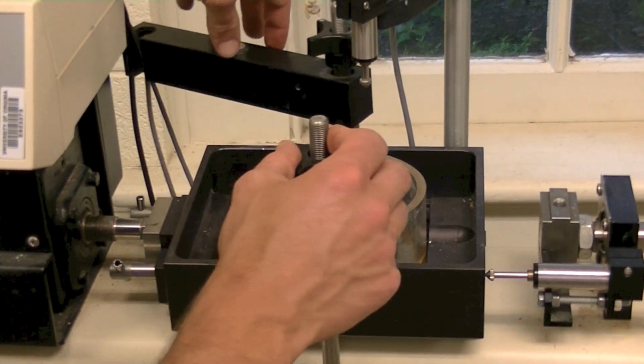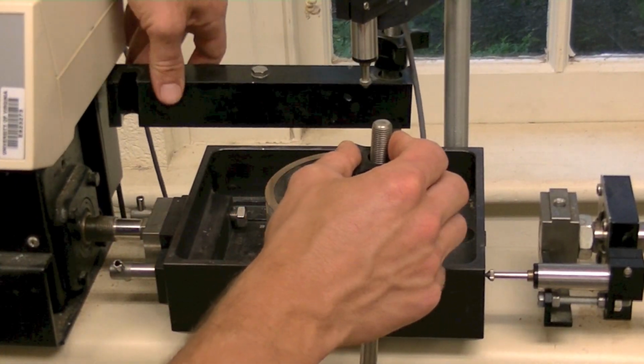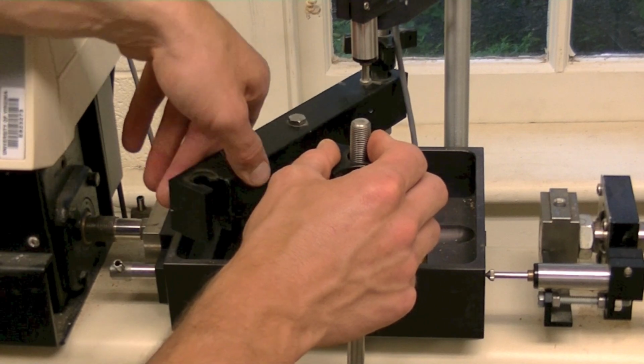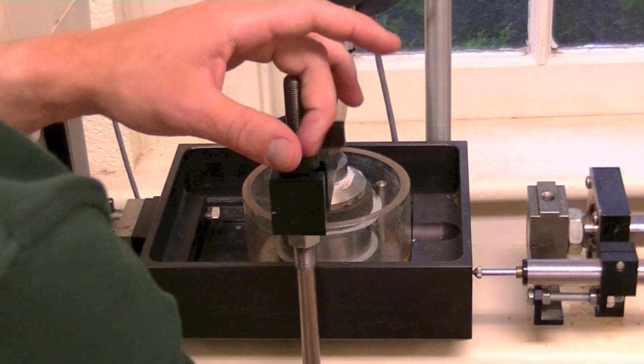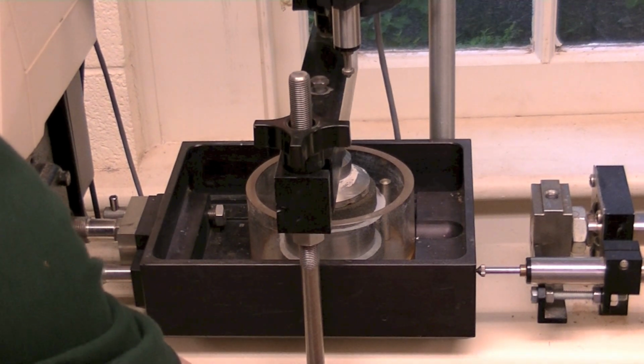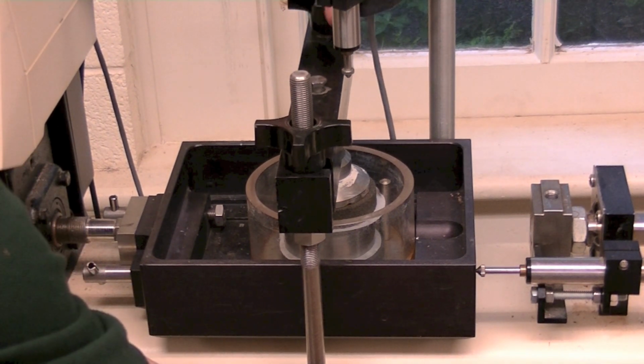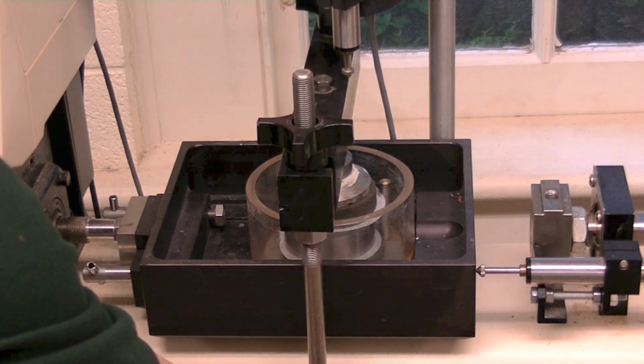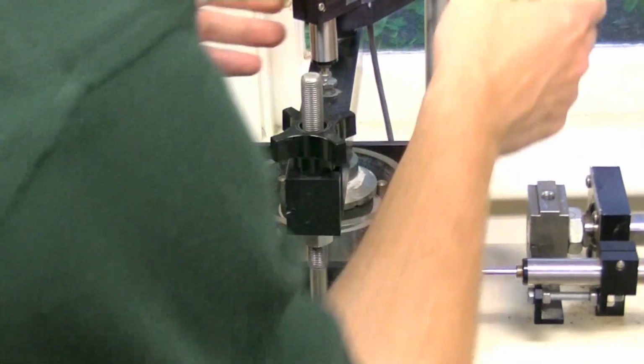Place the top platen and ball on top of the porous stone once the calibration disc is in the cup. Swing the load beam over and seat it on the ball. Tighten the wing nuts on both ends and ensure everything is flush with the calibration disc. Position the LVDT so that its tip rests on the load beam.